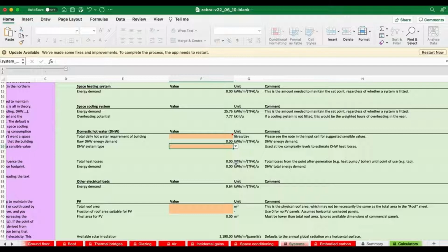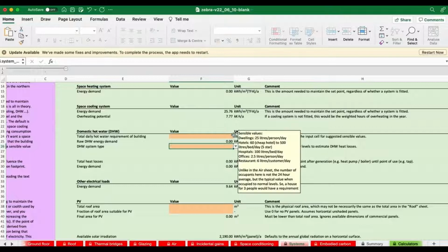And if you're trying to do a holistic design and drive towards zero carbon, that won't be very useful at all, because as we get more and more efficient buildings, you're needing less and less energy because of their insulation and air tightness. The percentage of the energy and carbon emissions from the building that's from domestic hot water and from plug use, etc., within the building starts to grow. So it's critical to include some information here.